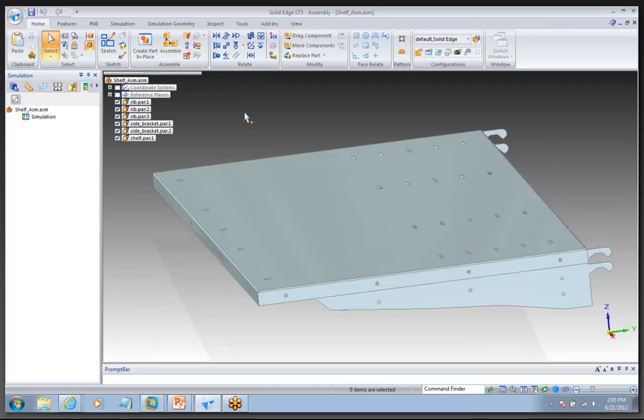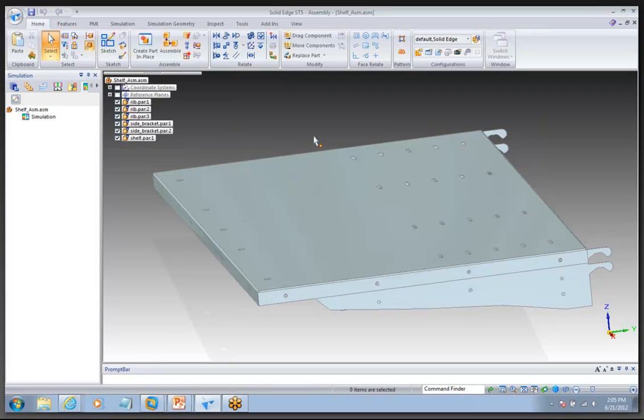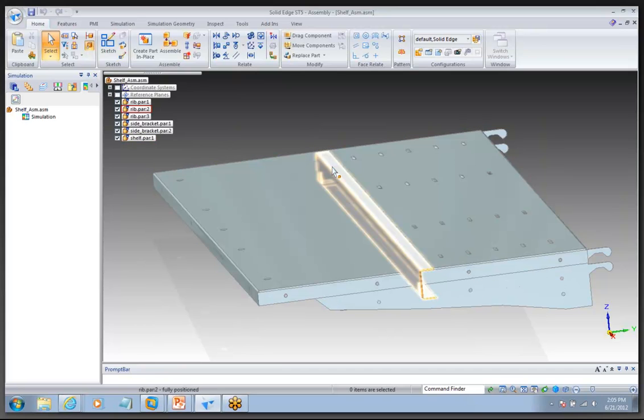simplifying the geometry. And the reason for this is because you guys have all seen a mesh. You know what it looks like. It's little triangles or squares all over this thing. The aspect ratio, which is in geometry check, is just a comparison of the length and the width of your element. And the element is just those little things in the mesh you see all over, the little triangles or rectangles. So the length to the width is the aspect ratio, and that should be around 1. You don't want to have a very distorted element or your results won't be good.